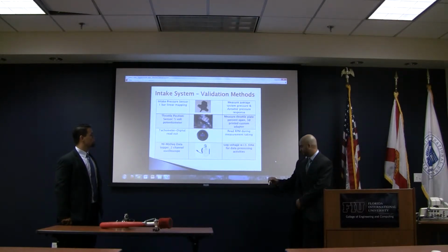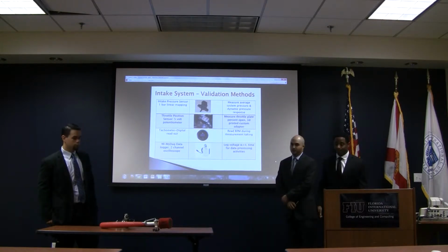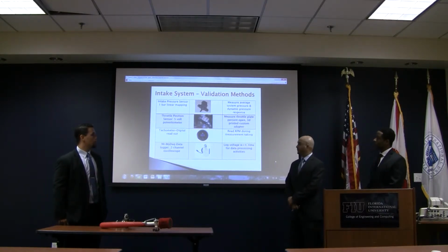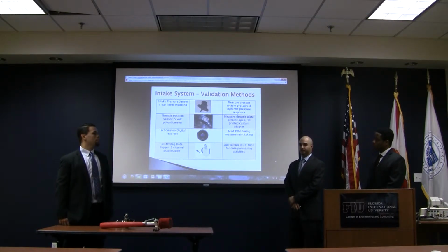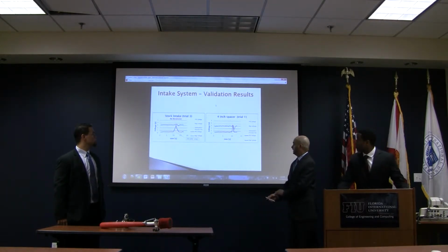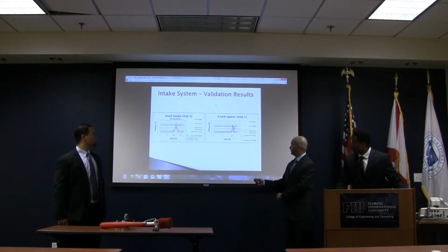Now my partner JP is going to talk about some validation. So our evaluation activity involved measuring the air intake pressure and the throttle position using a MIDAC 2-channel oscilloscope / data acquisition system. In this way, we can measure available engine airflow with respect to driver input or demand. The results of that data are these two graphs here.